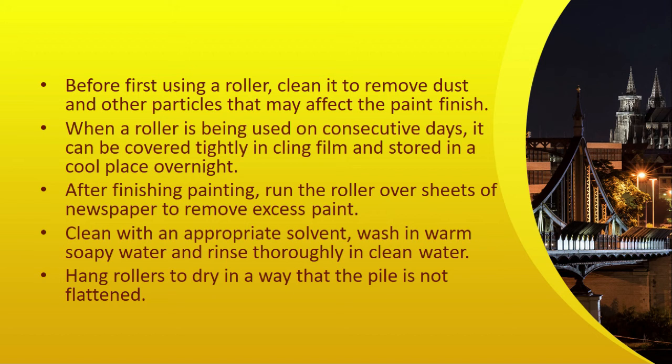Next is, after finishing painting, run the roller over sheets of newspaper to remove excess paint. Next is, clean it with an appropriate solvent and wash it in warm soapy water and rinse thoroughly in clean water. Hang rollers to dry in a way that the pile is not flattened.